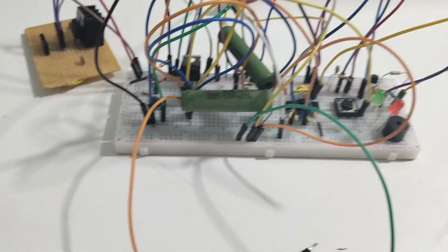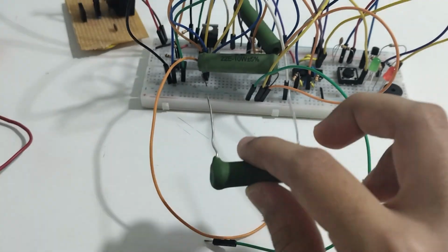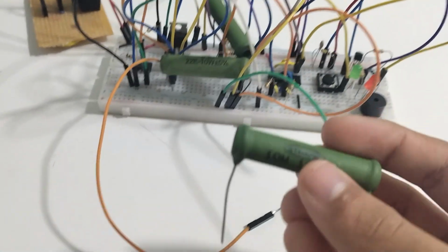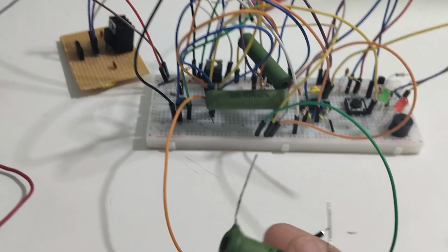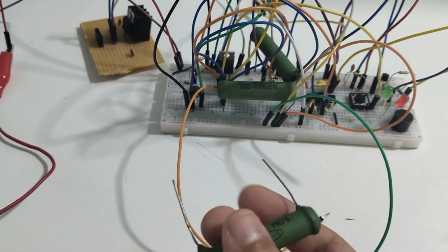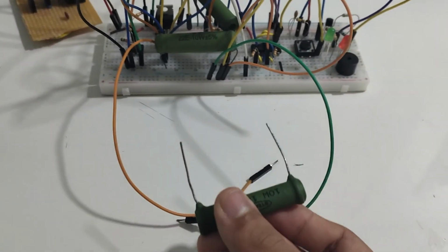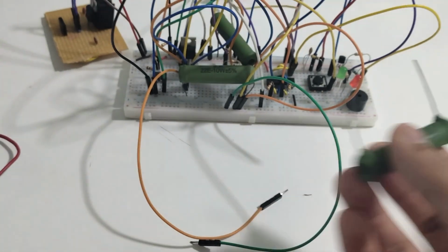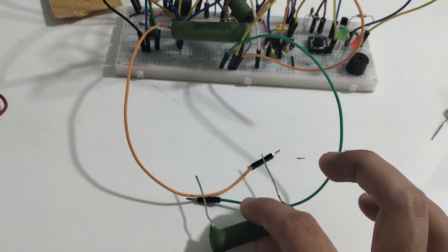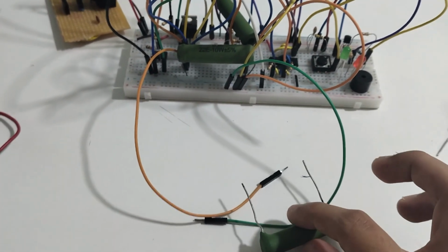And so when I put this in parallel with this, the current should continue to flow, the overcurrent should not trigger. But if I connect this 10 ohm over here, the resistance will become 7 ohm or something, and the current becomes around 1.7 amps, which is going to be above our set limit. So with this we'll be able to demonstrate that the overcurrent triggers, and I'm going to show you both to make sure of what triggers it and what doesn't.